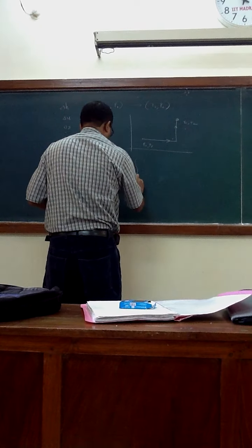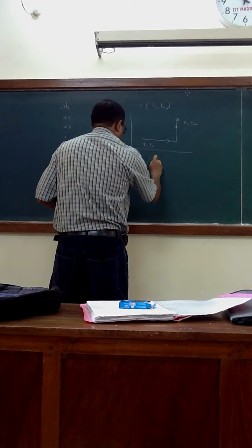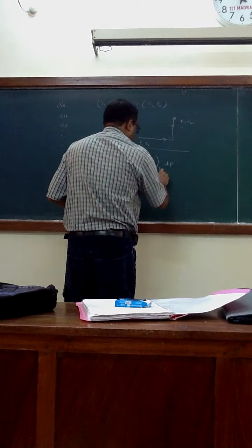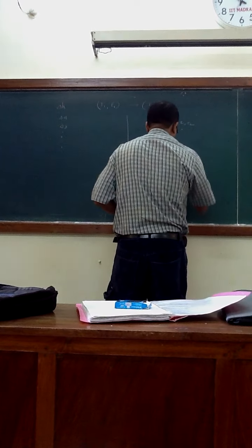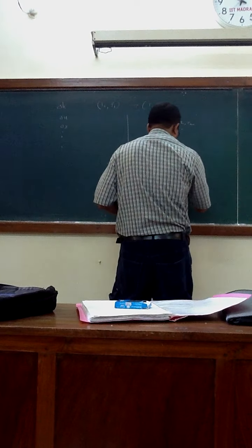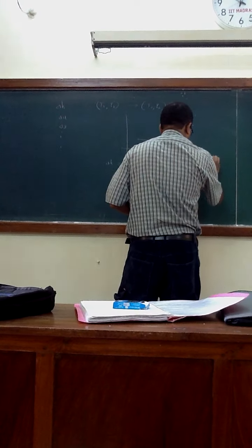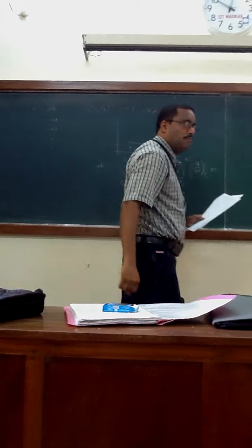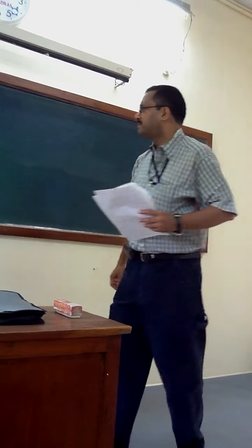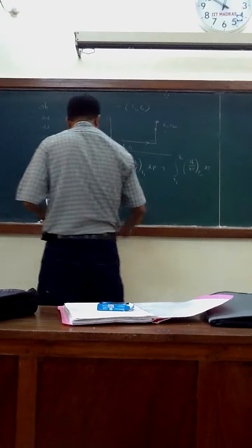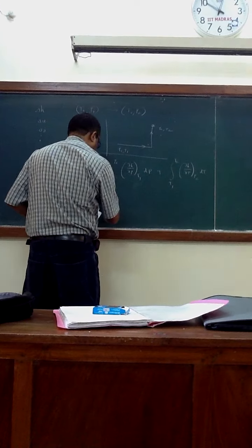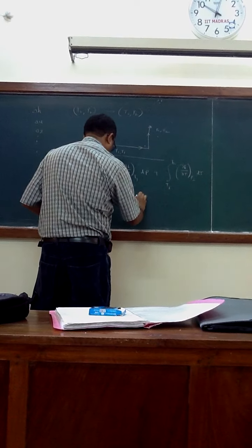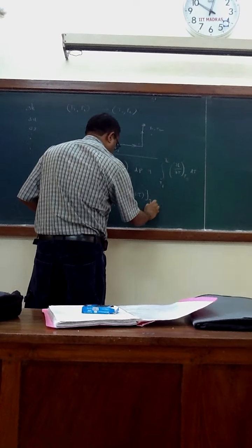That means if one would like to have the delta H for this, we first go from P1 to P2, integral of (∂H/∂P) at T1 dP, plus we go from T1 to T2, integral of (∂H/∂T) at P2, that is Cp dT. Right? This part is okay because we can write this as integral from P1 to P2 of V(1 − βT) at T1 dP.